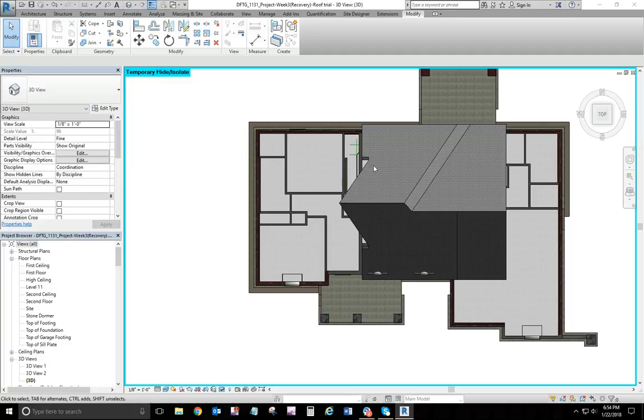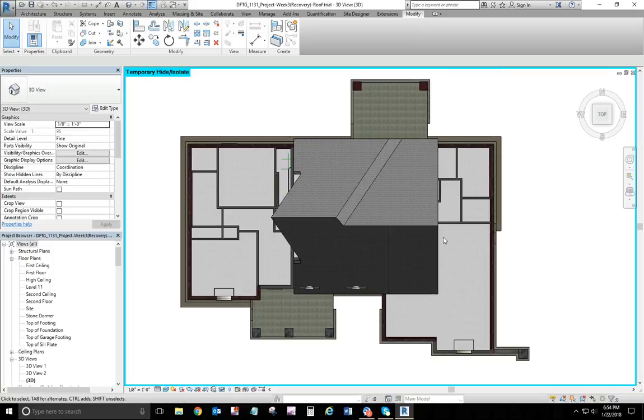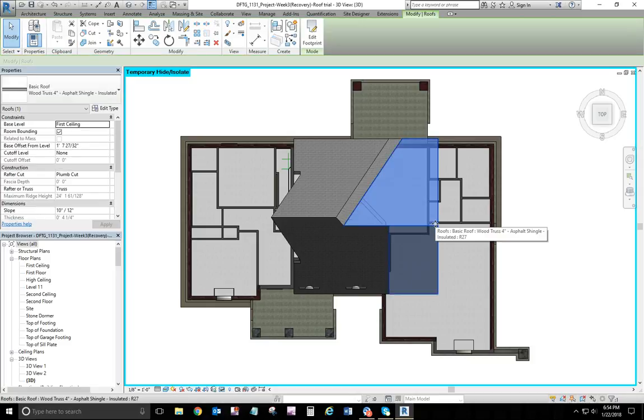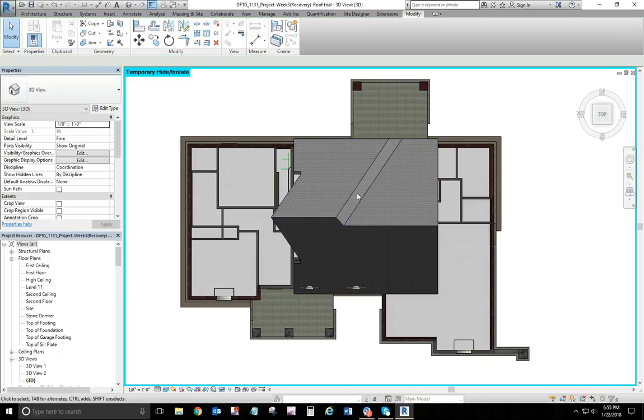Okay, so you can use the wall or the roof join tool here, right? That's what it's called. Yeah, roof join. You can join it to the other roof over here. Okay, but remember we did it as a rectangle. Then I came in and I did this one, and when you do this as a rectangle, it's not going to have this little whoop-de-doo right here in it. Okay. And then I turned this one back on.